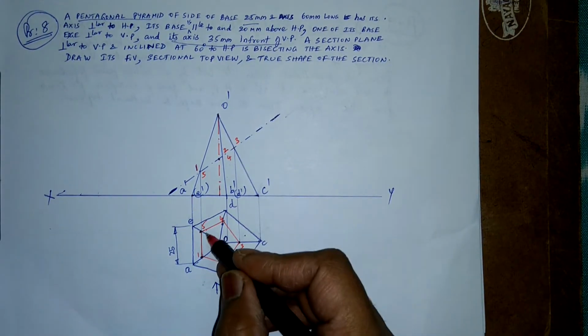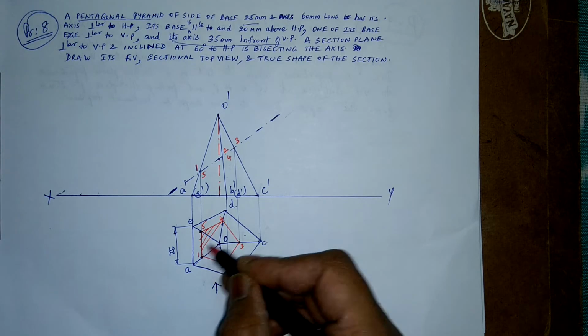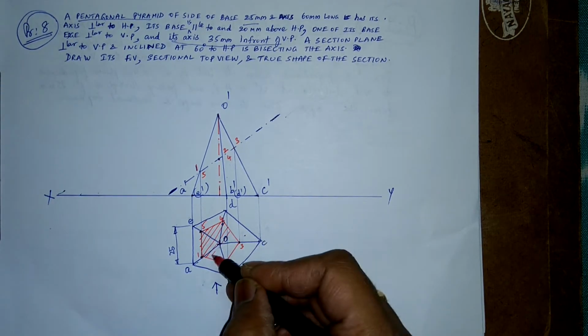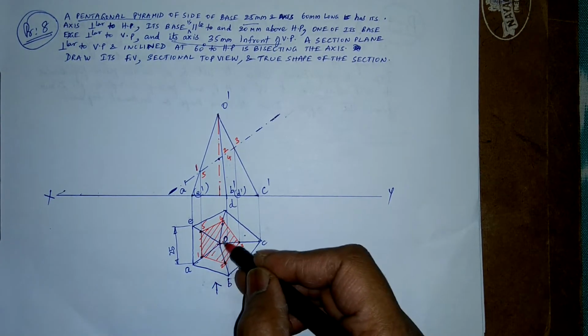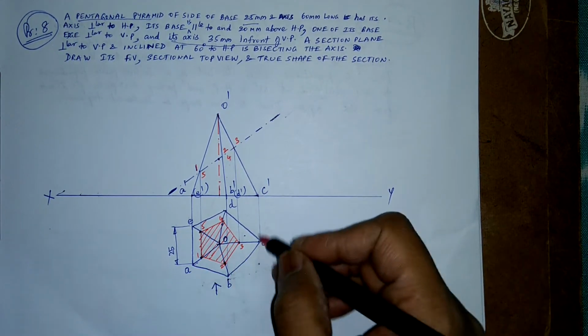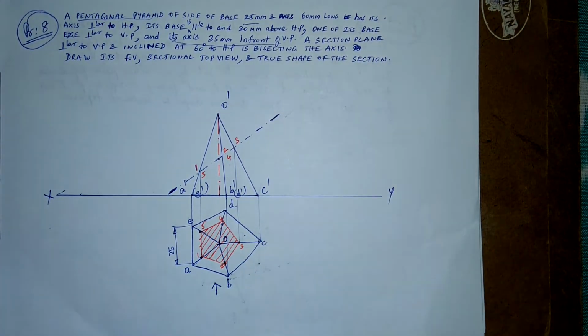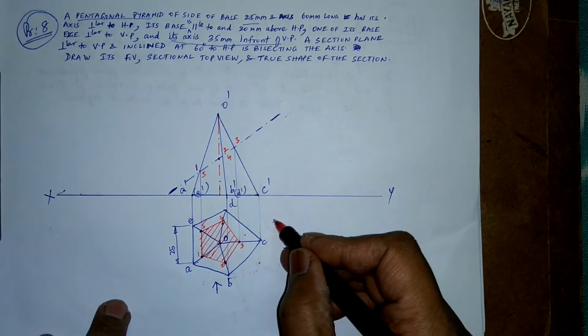So to the XY line, I'm setting 45 degrees on my drafter, and then I draw uniformly spaced lines. These are called hatching lines. I would use the 2H pencil for this. So 1, 2, 3, 4, 5. This is my sectional top view, as I told you.